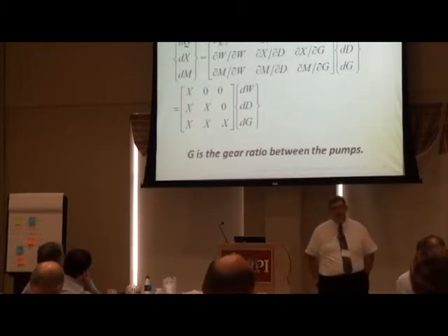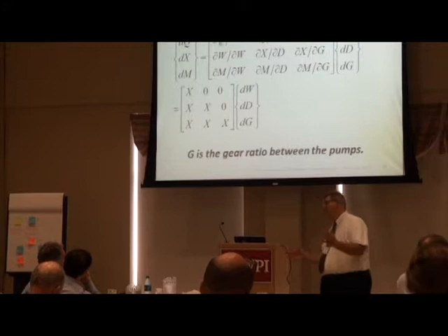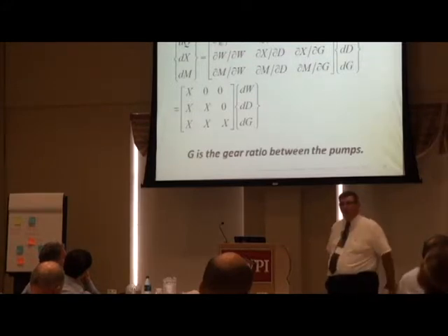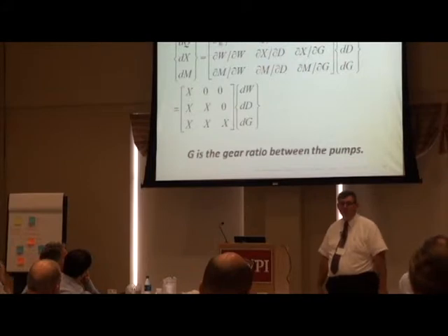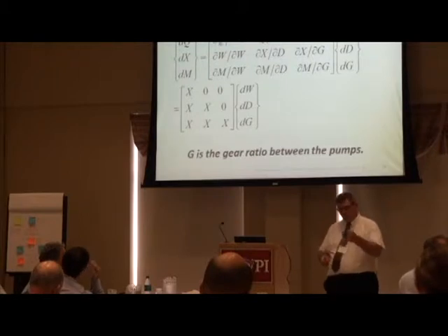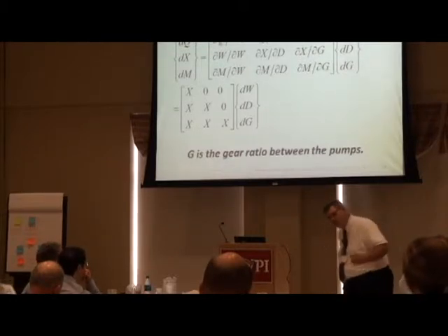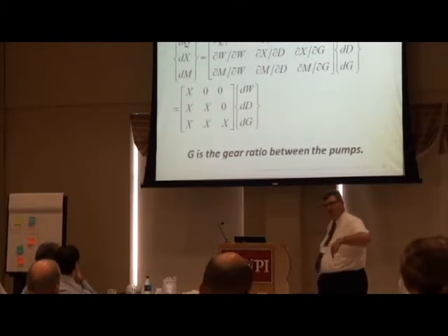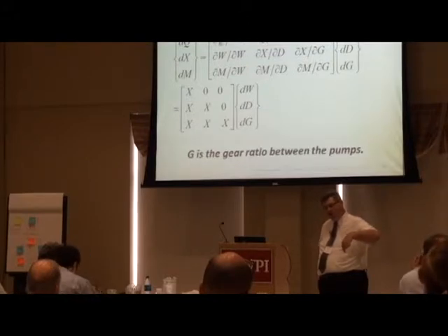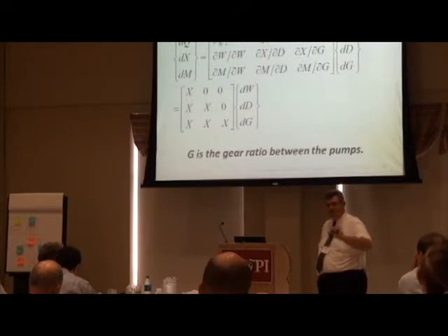I know a lot of the machinery that I've operated. I actually have personally operated many laser cutting machine tools that cut metals, big sheets of metal. And a laser is really kind of cool because you got this really high power beam of light with a magnifying glass on it that makes a spot. And you have a certain amount of energy that you put into it. And so as the laser is traveling along and it's melting the material and essentially blowing it out of the way, you want to go as fast as you can without going so fast that the energy can't get distributed over the thickness of the material and complete the melt.